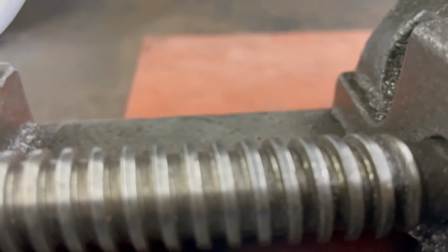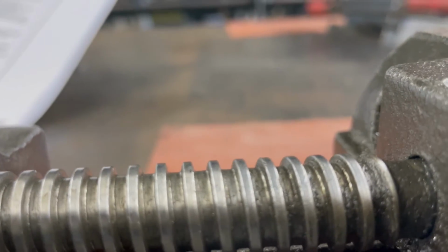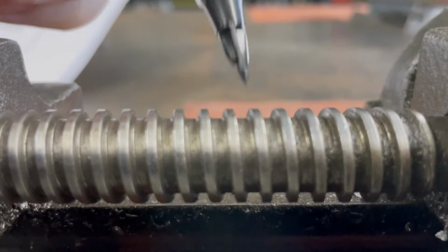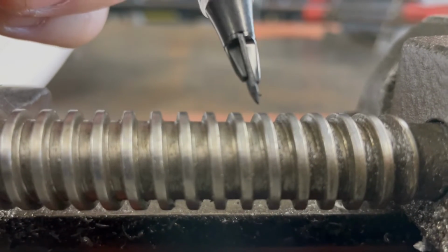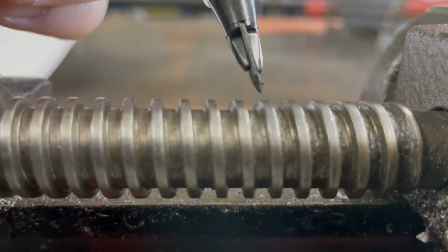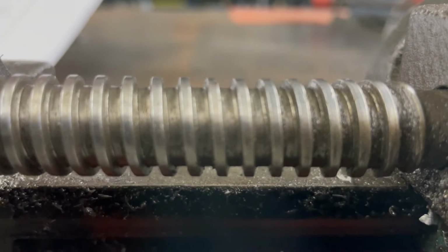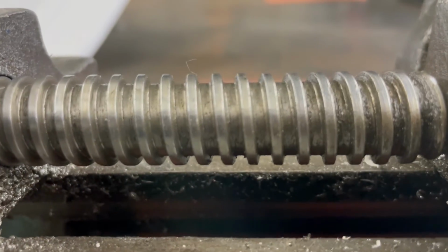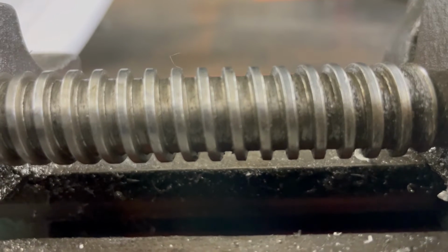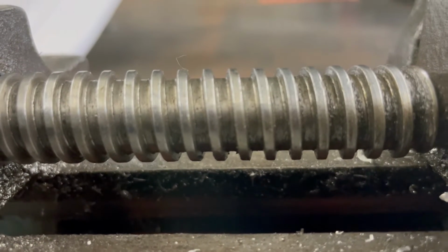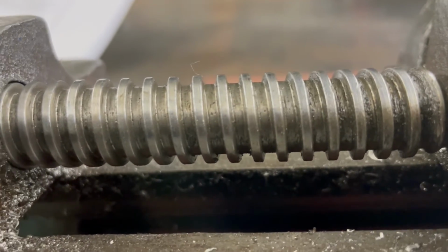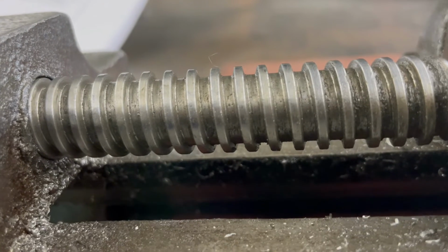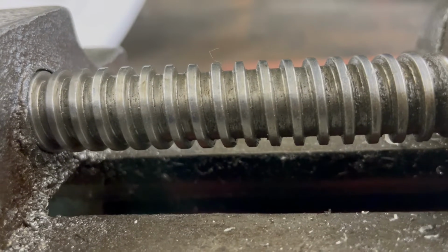So here's an example of an Acme thread. Acme threads have a very, very slight angle on the flank, and then they have a squared-off crest. These are good for clamps, vices, that kind of thing. They're robust, as in they don't have a point that, if something drops and nicks it, is going to muck up the fit between the internal and external. They're quite strong, and they won't lock up because the actual push is coming straight in line with the axis of the screw.